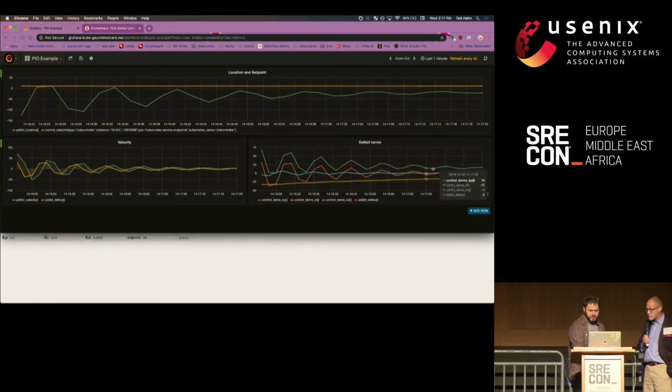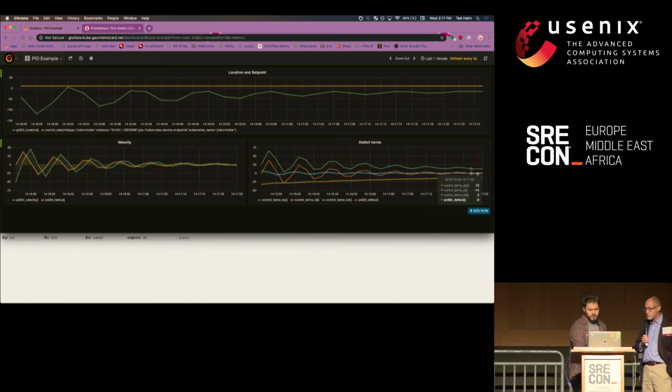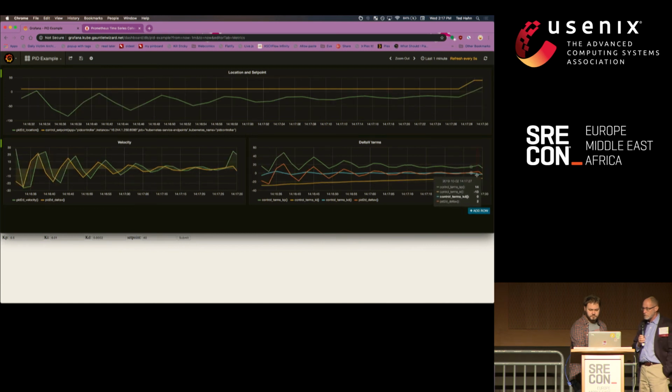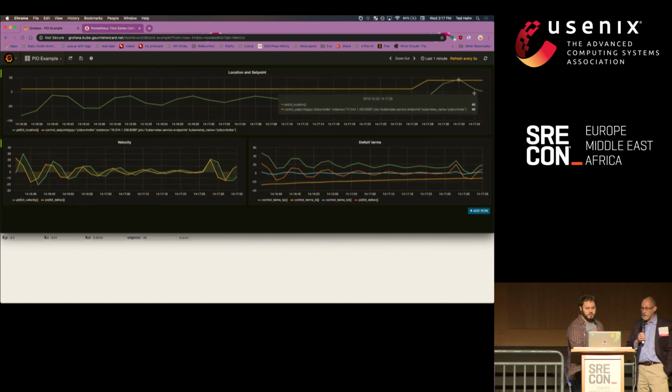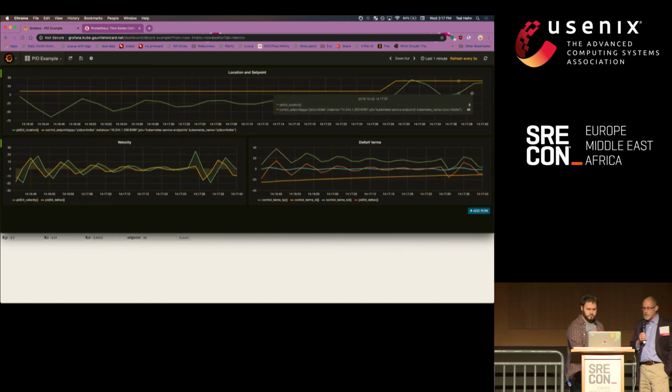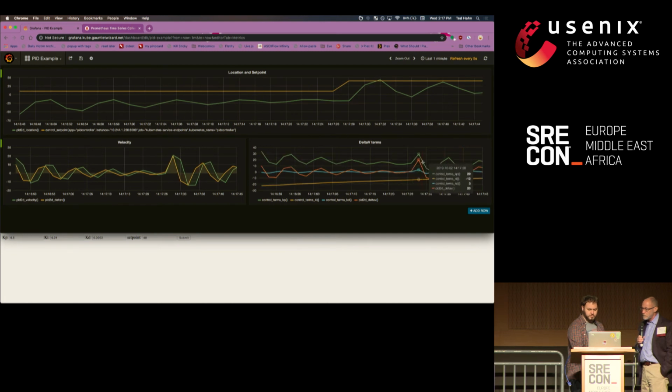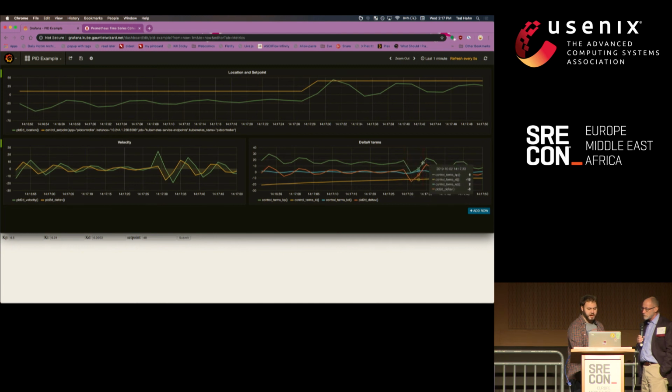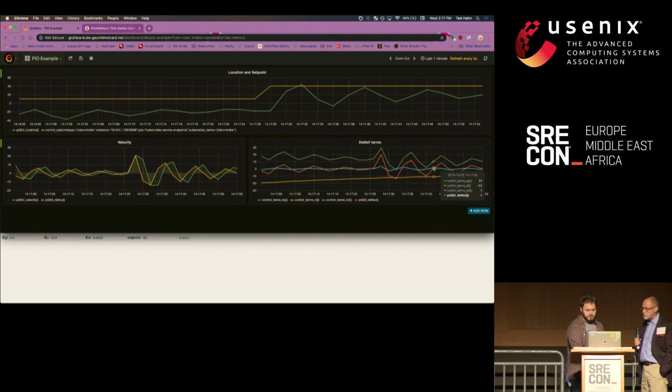So you can see that the 3 terms here will start to change as soon as it actually picks it up. Okay, so our set point has adjusted. The set point's the yellow line, and the process variable, the actual variable that we're trying to create in the system, is the green line. The proportional portion, as well as our overall delta V, went up in response to that, and then the derivative term pulled it back down to prevent overshoot.